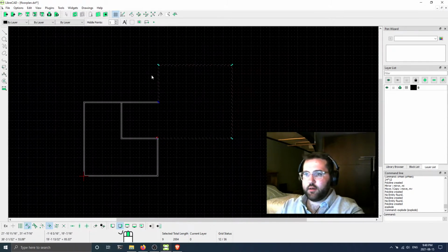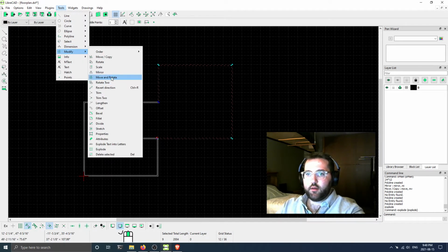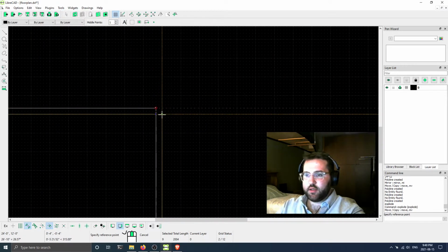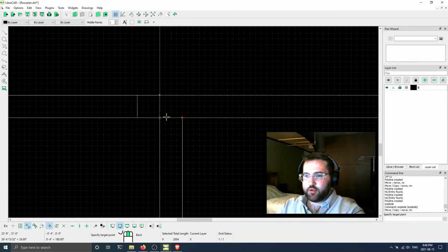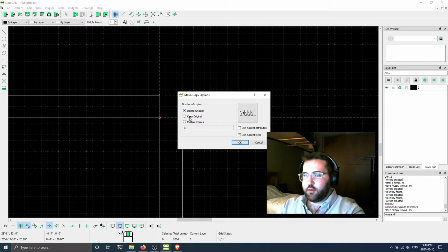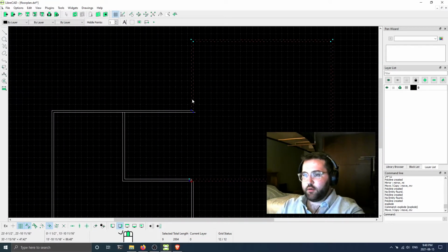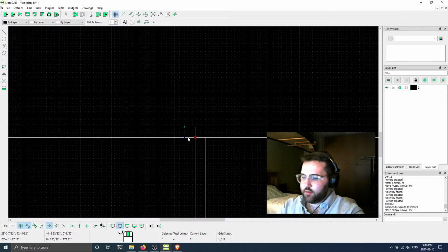So I'm going to have that area selected, and then if I go Tools, Modify, Move/Copy, and then I'm going to select this as the base point, and then if I just drag across here, I can just choose Snap to Grid, and then I'll delete original, and I'll move what I drew there earlier 4 inches to the left. Now obviously these line segments don't align anymore.